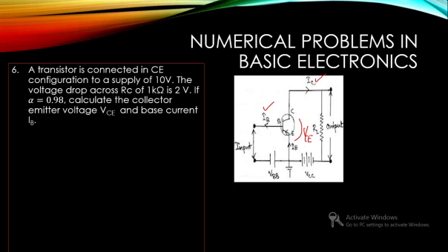So how do you get VCE? Yeah, this is from the supply VCC. So will you get the total VCC to be dropped across the collector and emitter? No, because it has to travel along a resistance path RL. So there would be, with respect to the current, that is collector current, the output current or the current in that circuit, a voltage drop. So VCC minus this voltage drop will give the voltage across collector and emitter.